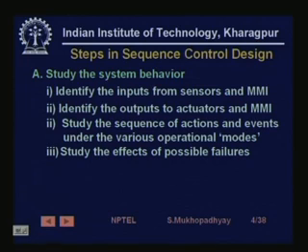Then one thing that must be very clearly remembered is that when you are developing an industrial automation program, one not only has to design for normal behavior, but one must, to some extent at least, take into account the possible failures that can occur. Otherwise, a system that behaves well under normal behavior can behave in a very nasty manner if some simple element of the system like a sensor fails.